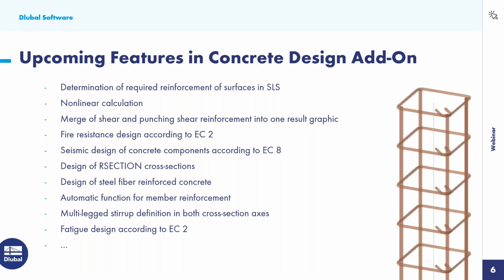So the same determination of required reinforcement like I have shown to you for the members, with the option in the SLS configuration, we are also developing the same option for the surfaces. Then nonlinear calculation is also in development for ultimate limit state and serviceability limit state for slabs and members or beams.